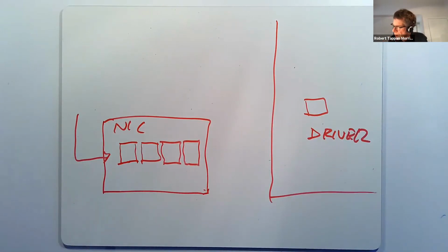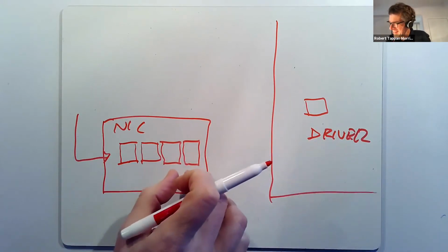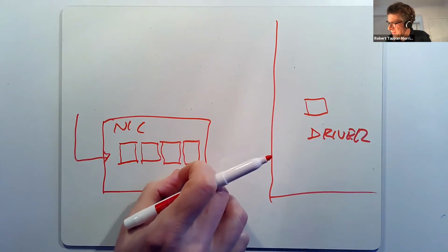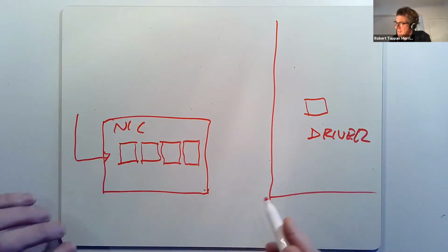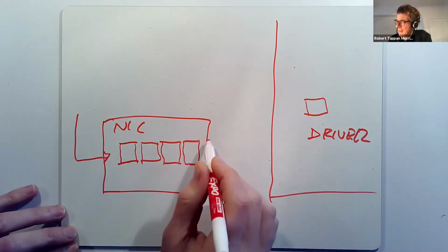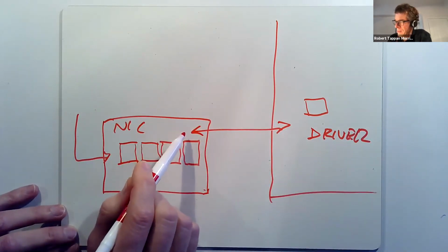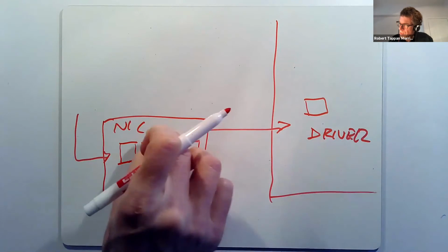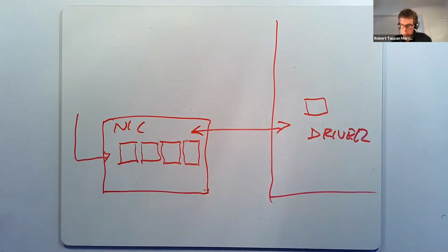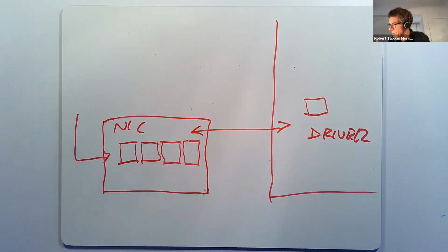That made a lot of sense 30 years ago. Today, though, it turns out that loops in the CPU that copy, that talk to external hardware or hardware sitting on buses, are very, very slow. In the grand scheme of microprocessor design, the distance between the CPU and an external device, even if it's on the same computer, is a very long distance. Each conversation takes a long time for each back and forth chit chat. So you don't want a lot of byte by byte interaction, and people don't design high-speed interfaces like this anymore.